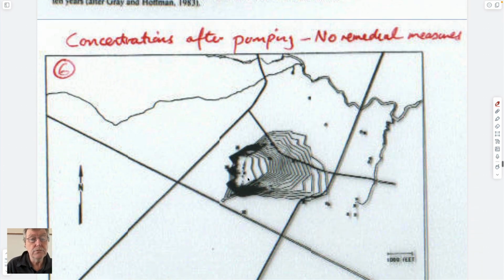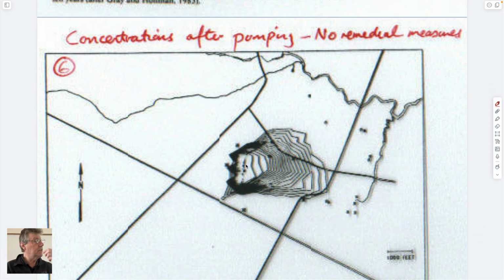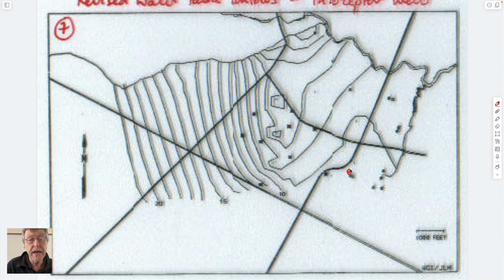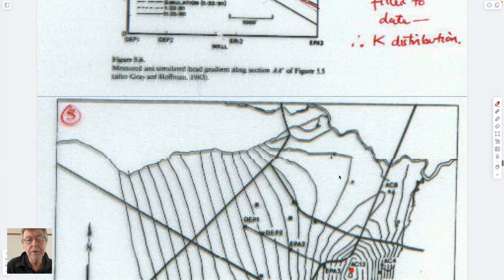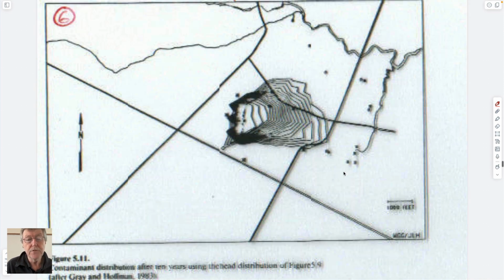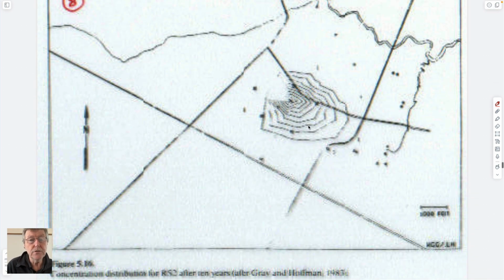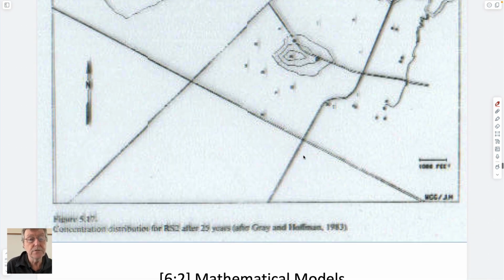And you turn it on to look, overprinted on the groundwater flow, at exactly what the transport of the mass components dissolved in the groundwater system is. And so you run the model to look at the plume and to define how, if you start pumping very heavily out of this area, instead of just pumping for domestic use, you really start pumping water out of this area with interceptor wells, maybe placed here and here, you can mitigate and remove the plume as it goes downstream, so you shrink it over time.